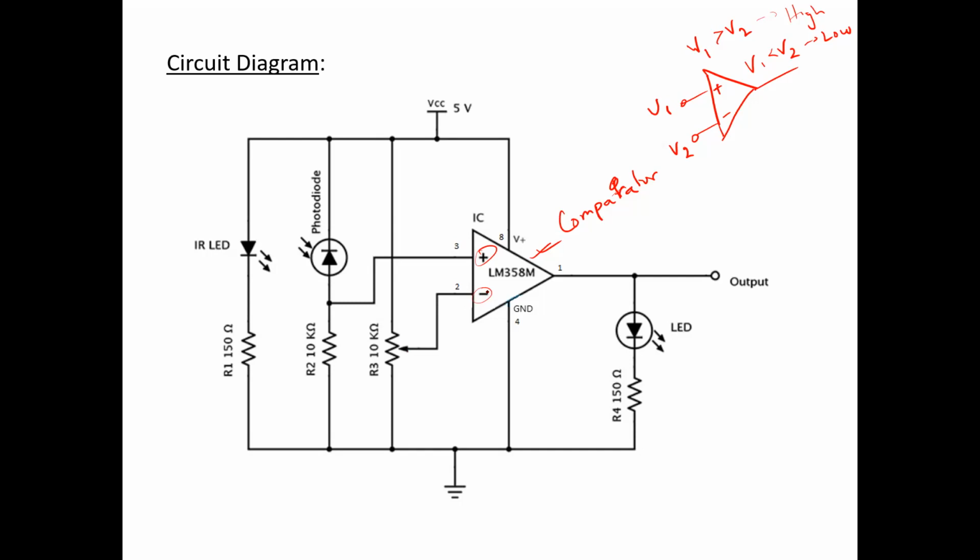So the inverting terminal input is coming actually from the potentiometer. The 2 fixed terminals of the potentiometer are connected across the 5-volt supply and ground. Depending upon the position of the sliding contact, the sliding contact is actually connected with this inverting terminal. So wherever the sliding contact is located, there will be a voltage division between the 2 components of the resistance in the potentiometer.